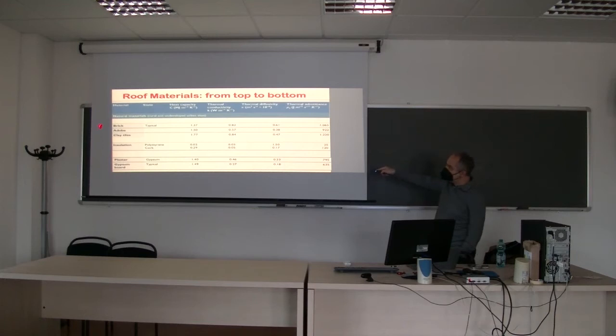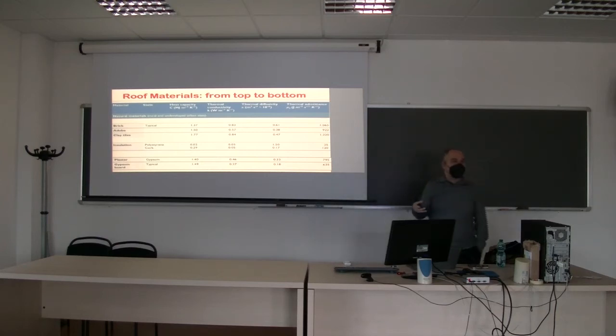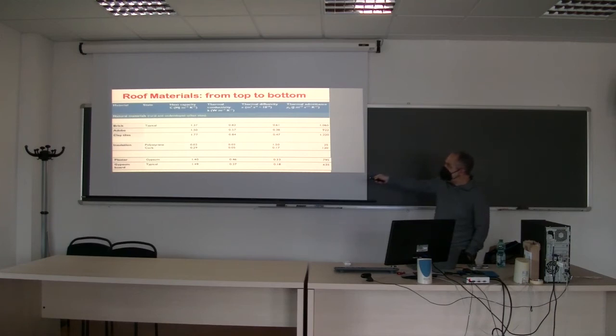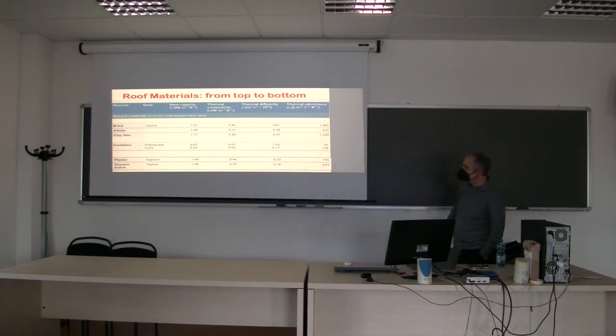So you see that some of the old materials that we used to use, like clay or adobe or brick or plaster or gypsum, have very high thermal admittance, so they're not good insulators. This is why old buildings have these very thick, huge walls. You increase the mass and the thickness to compensate for this large admittance. With the more modern materials, polystyrene and cork, you can have a much thinner insulation that gives you a similar effect, because they both conduct less and store less, and this is a good combination to reduce the thermal effusivity and potentially the diffusivity.